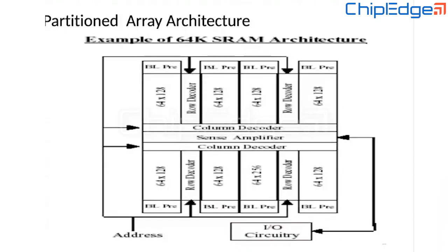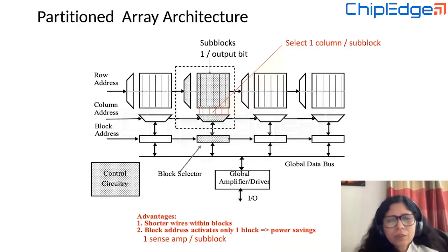Okay. So, as I mentioned, these word line and bit line play a very important role, right? So we know that they are capacitances because these are the signals which are running all across the memory. These are very important and heavily loaded signals. So to gain on access time, to gain in the frequency of operation, a lot of times, when the memory size increases, we can't continue to have one single SRAM array. So we partition that to reduce the load or the run length of the word line or the bit line.